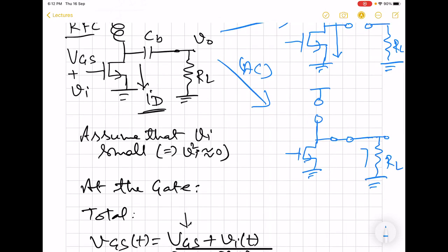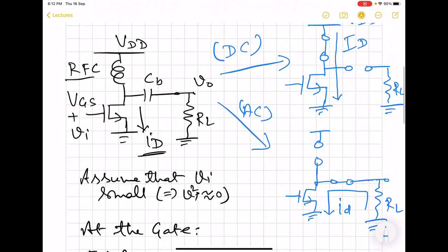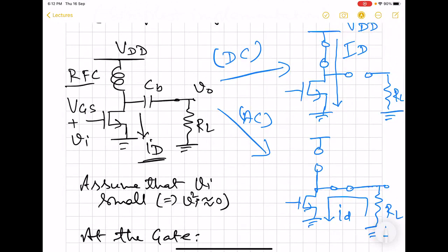So we see that the time varying drain current is going to take this path. So finding the equivalent circuit and more specifically the path for different components of drain current is important. This we will be carrying out for all the subsequent power amplifiers, and this will allow us to find the drain efficiency.